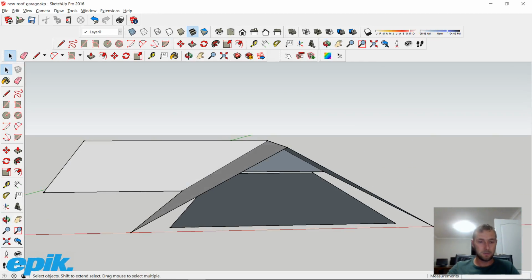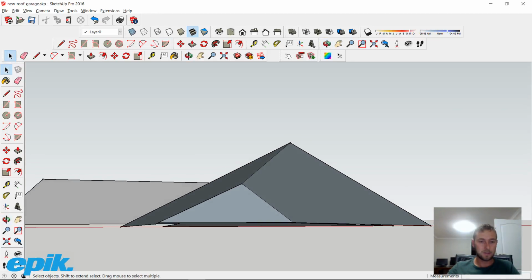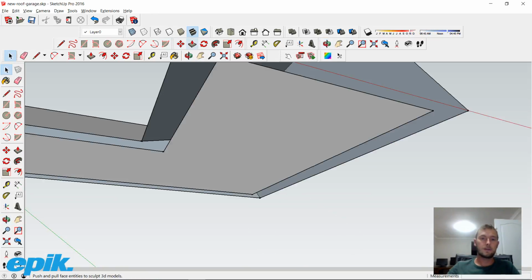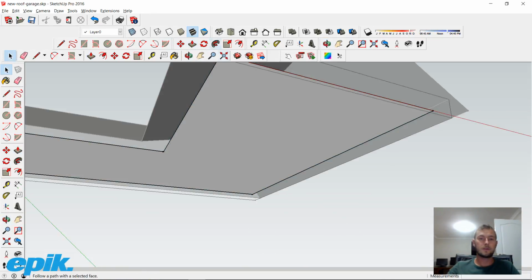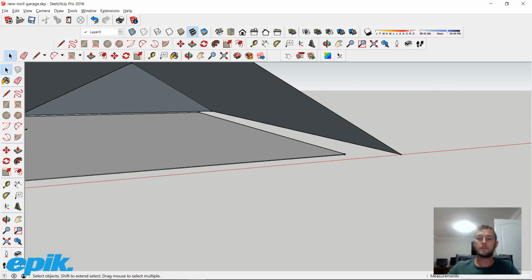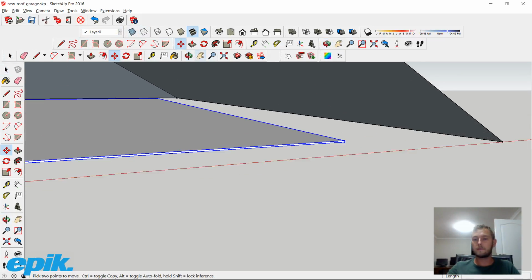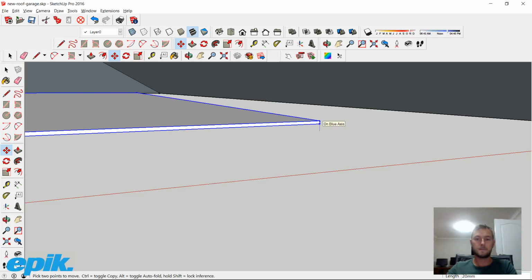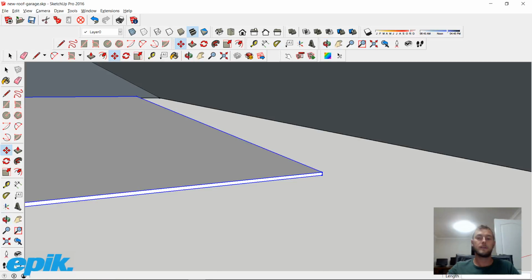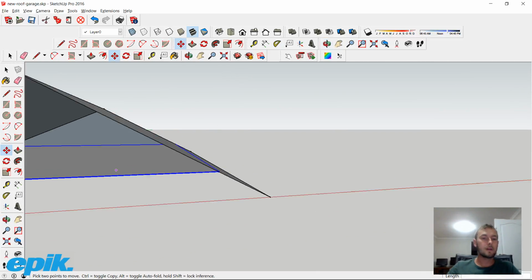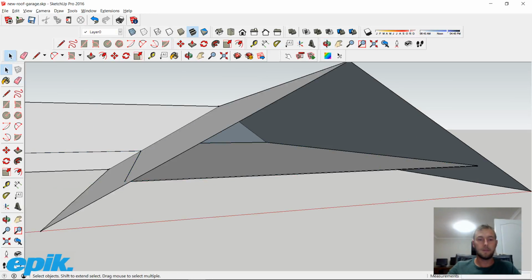The ceiling's not exactly in the right place right now. The ceiling will never sit flush with the edge of the roof or overhang the roof. It'll sit within the roof. So let's give this a little bit of thickness, get into the group, open it up. I'll just choose 6 millimeters, just because. What I'm going to do now, with the blue axis selected, just push it up to clip to the blue axis. Just move it up until it touches that face. Your ceiling is now in place.